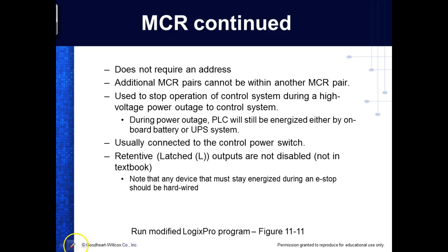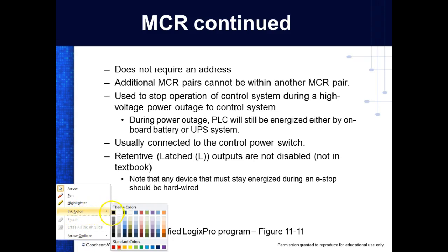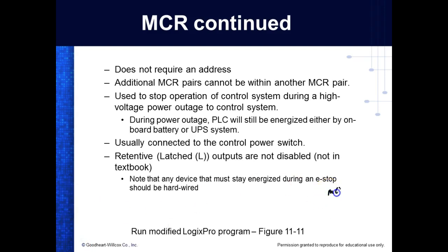I can do this. I could have an MCR, and then I could go down to some instruction, and then I could have another MCR. I can't put an MCR within an MCR. Now I could come over here, have an MCR, come down through some instructions, put another MCR, then down here put an MCR, and then have another MCR, right? Because they're not within each other. So you can't have an MCR within an MCR. Understand what I'm saying? Okay.